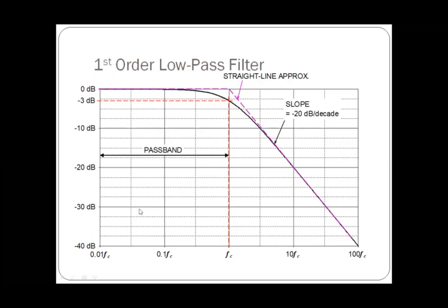So as this is a low pass filter of passive network, what we are discussing now, because of that the gain will be 0 dB, because for a passive network the maximum gain will be 1. So if you take the logarithmic value, so then the maximum gain will be 0 dB. So we are going to consider the 3 dB frequency for this. That means 3 dB below the maximum value.